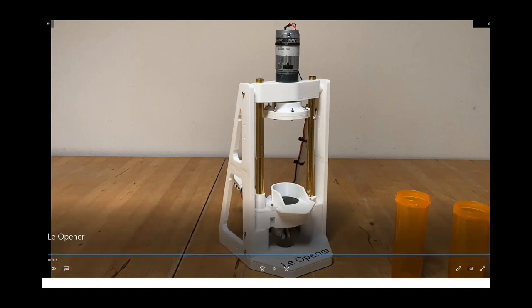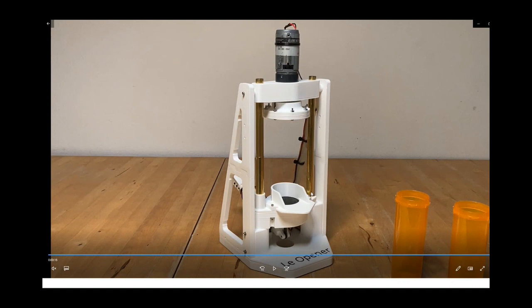Basically, these are hollow brass tubes. I have a hollow tube sleeve that goes out, and I want to be able to be accurate to slide up and down. So you have one moving part, which is 6 degrees of freedom. I have a cylindrical joint, which is a value of 4. And over here, I have what you call an end plane joint. It's basically like a fork that goes around a rod, so it keeps it from rotating basically. And that's all it needed.